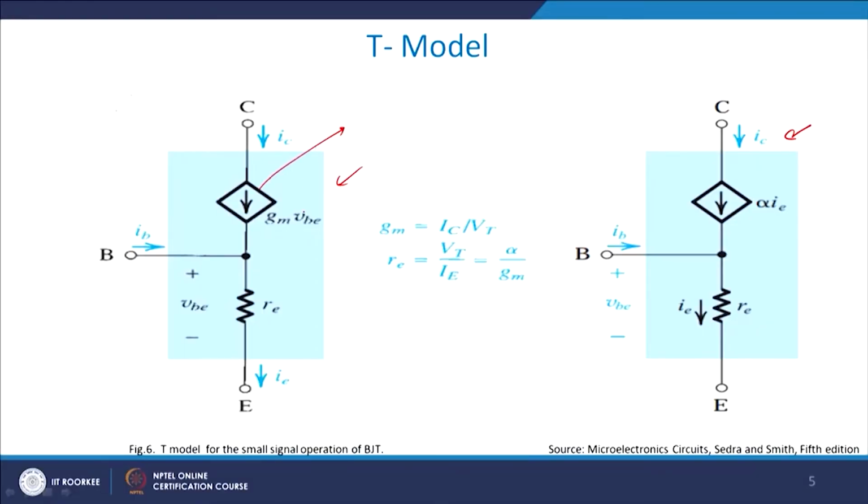So I get RE here, the voltage across RE is basically my VBE, base to emitter voltage, and this is the applied voltage which you see. The current direction is of course the conventional current direction, as we have been discussing quite often, and therefore the collector current will be equal to GM times VBE. We have again discussed this point as the input point.